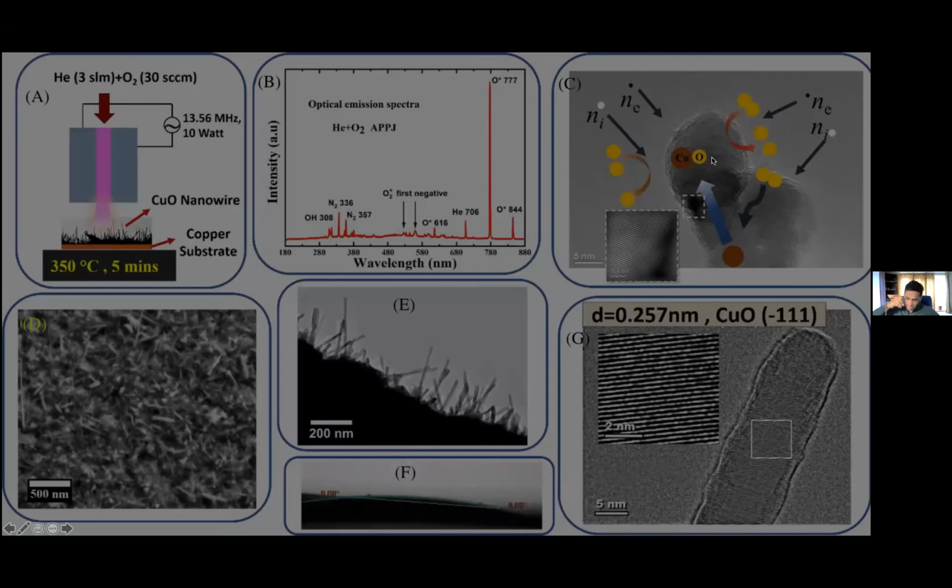When we put plasma on the system for less than 2 minutes, initially the radicals in the plasma interact with the surfaces of the copper, and then we slightly heat the system to about 300 degrees, linear expansion happens, and that involves pulling off the catalyst, the copper oxide, from the surfaces. So that is pretty much what we were thinking was happening.